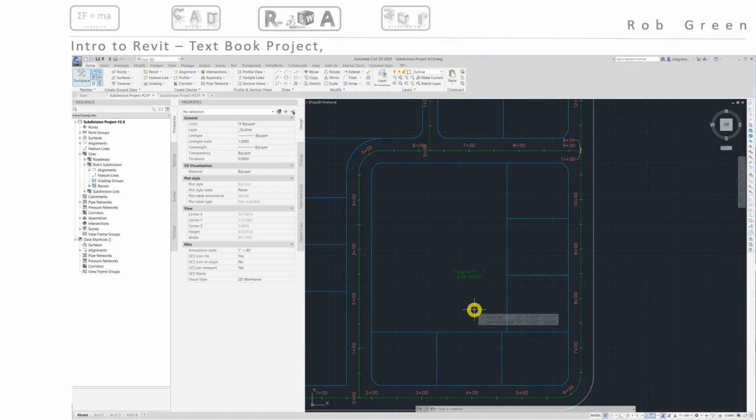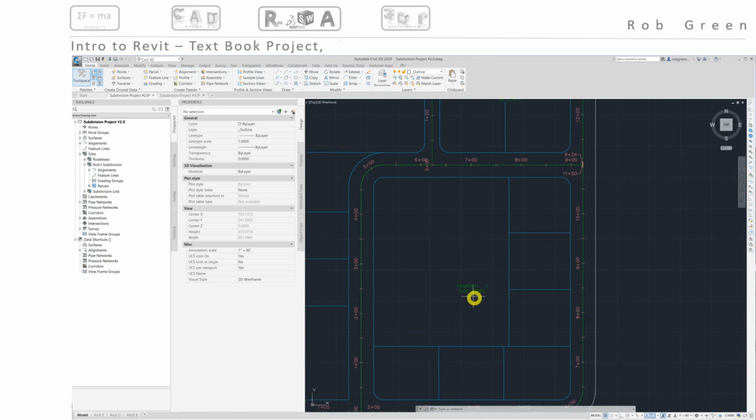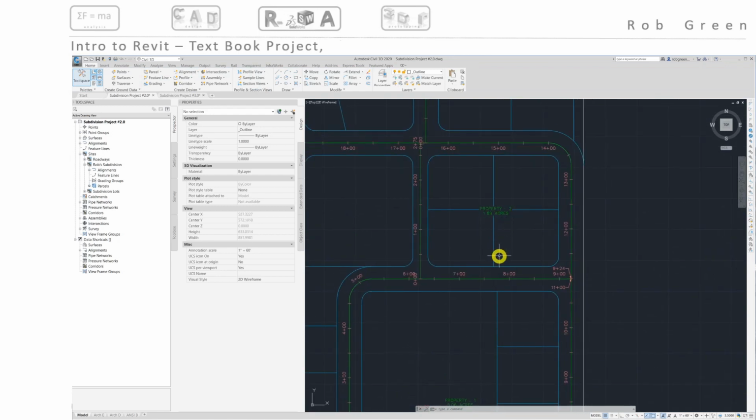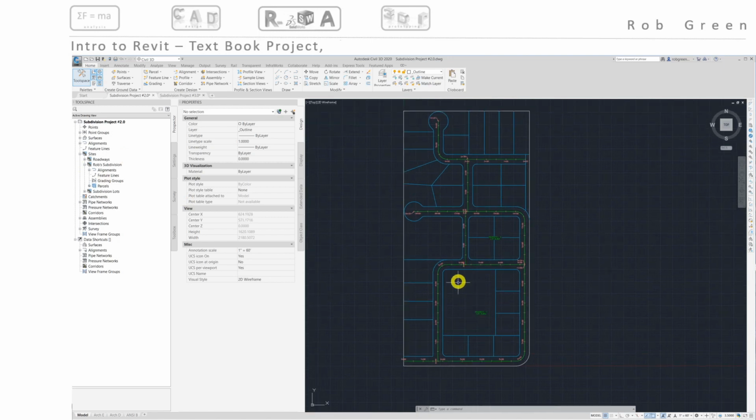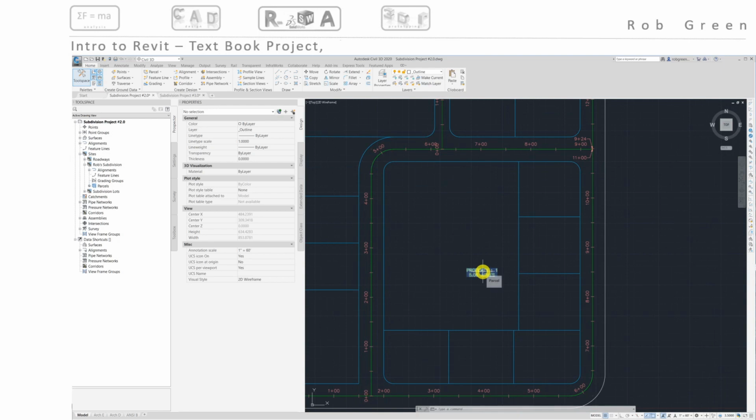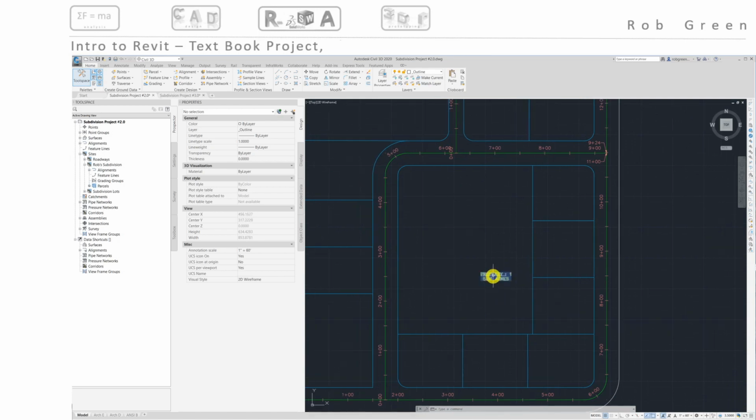And I will say what you will notice is that we also have two pieces of graffiti sticking here. There's property 1, 5.06 acres, and property 2, 1.89 acres. And the question is, well, what is up with that and what is it? So Civil 3D, remember we have a site, and every time Civil 3D sees a civil entity completely enclosed, Civil 3D is going to begin to divide out this land. So what's enclosed is going to get a particular database property, and this database property is saying that the amount of land that exists inside this alignment is 5.06 acres. And I'm guessing that your project doesn't look like this. It says something else. We'll deal with that in a few minutes.